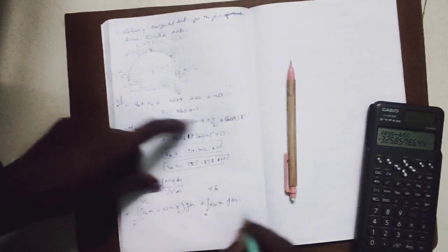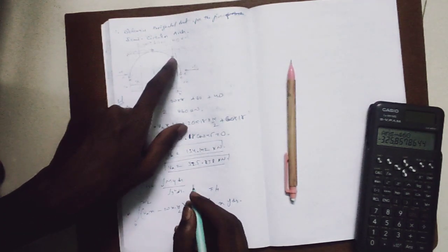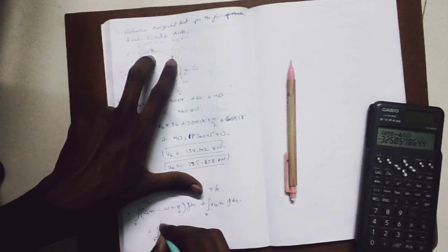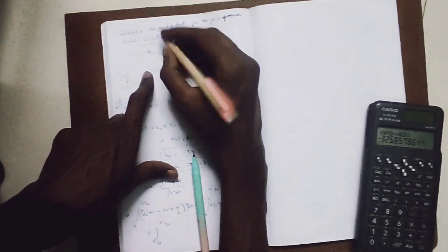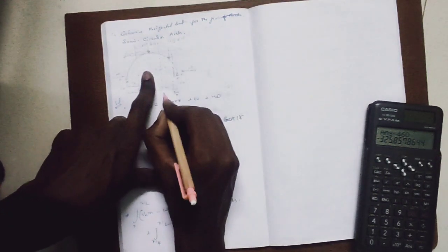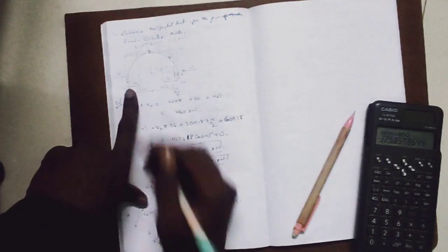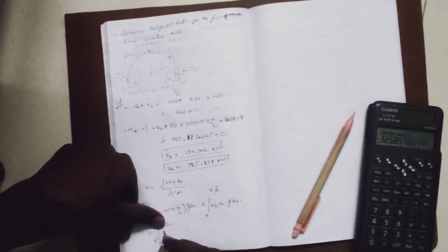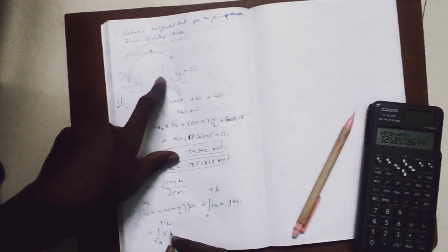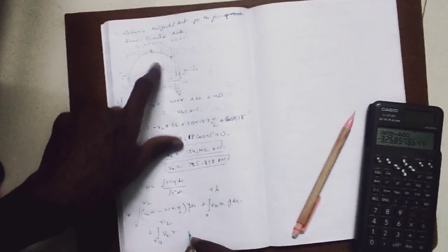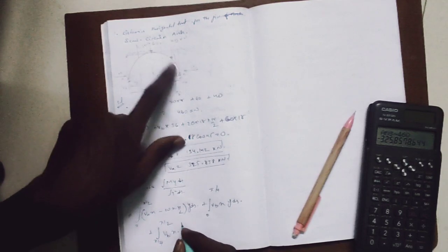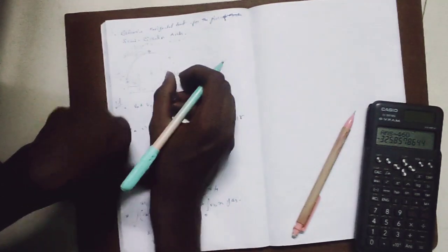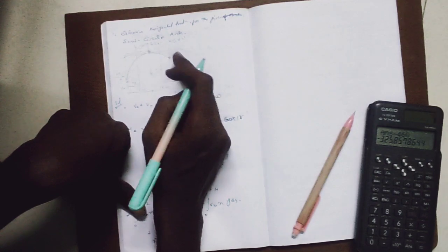So y ds. Now we'll consider a section between these two points, that is pi by 4 to pi by 2, right? We'll consider a section here, which is at x meters distance, the same x. So we'll write a moment for that section: VB into x minus 40 into, what is the distance for this?